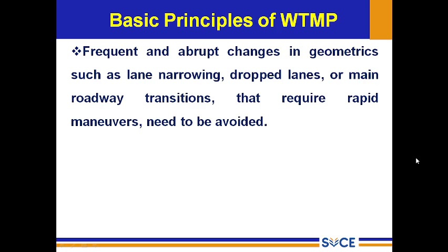Buffer zone, this much distance depends upon the road geometry or road design speeds, expected speeds. So accordingly, and at night time proper lighting facility should be there. And sudden change, sudden road closure, those things will cause confusion to the driver. There shouldn't be any confusion. Clearly, it should be done.